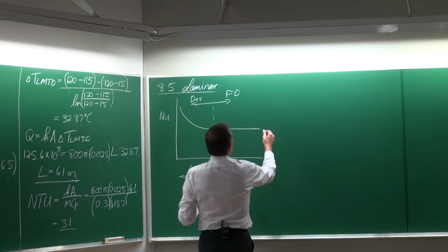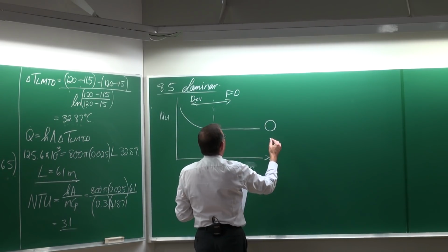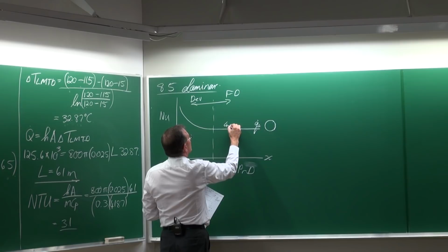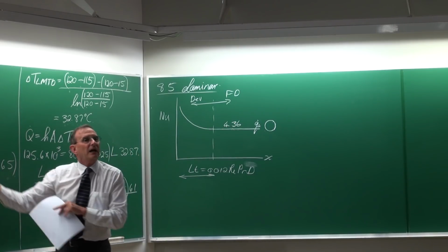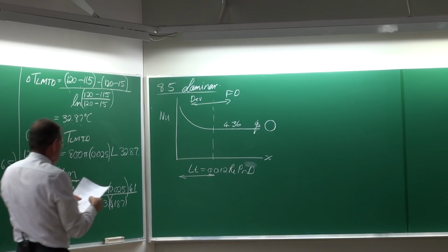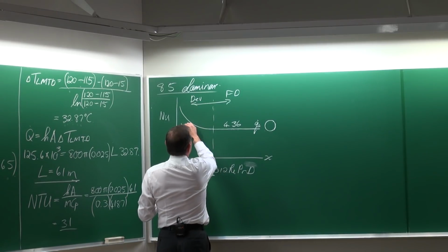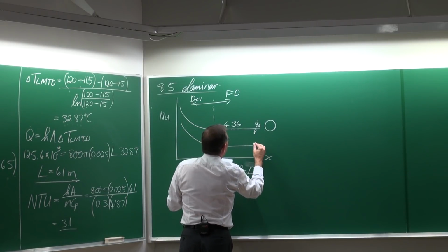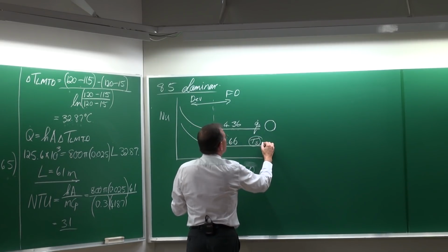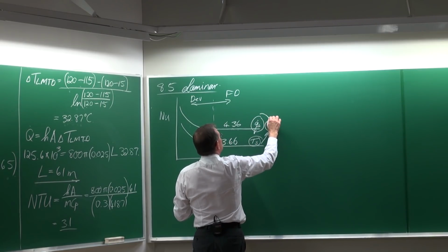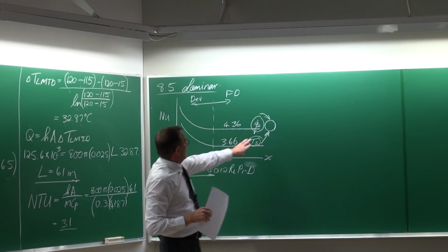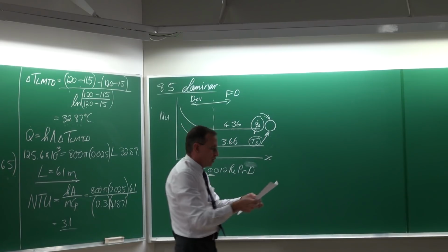Now, if the tube is circular and we've got a constant heat flux, then the Nusselt number would be equal to 4.36, and you can calculate it analytically. You can also do it for a constant wall temperature. For a constant wall temperature, it would be equal to 3.66. So both of them are for a circular tube. And again, I want to emphasize it's for a circular tube, so there are other geometries also.